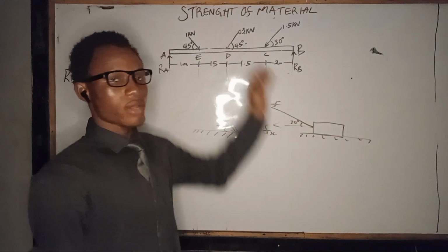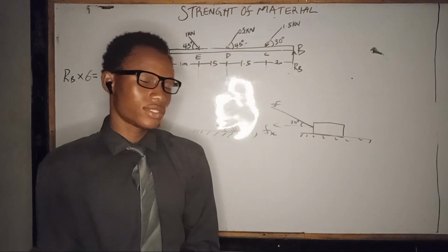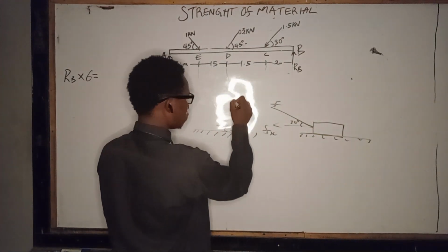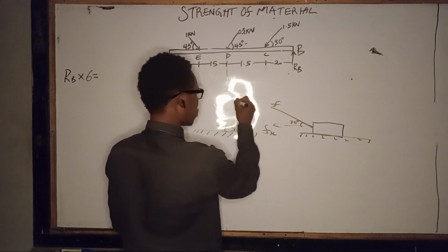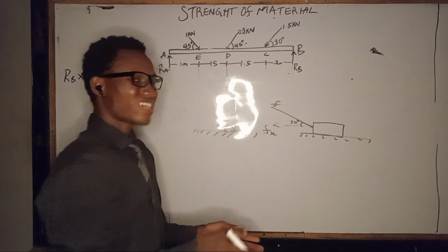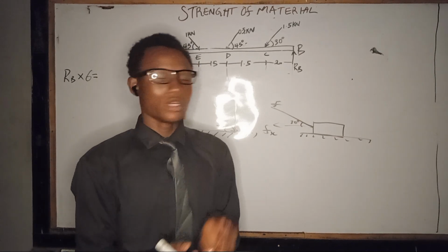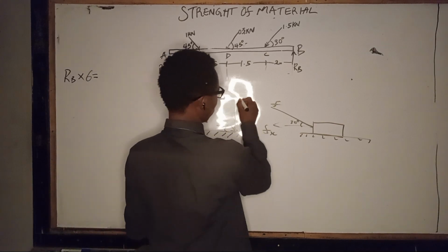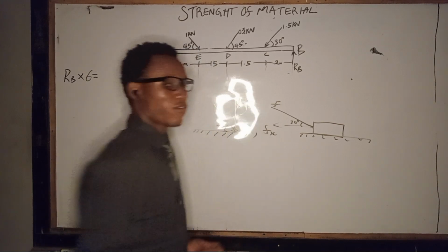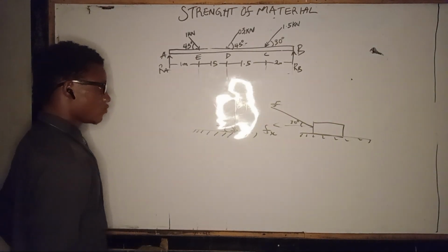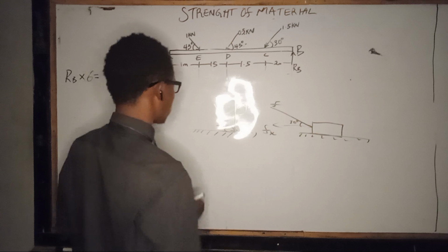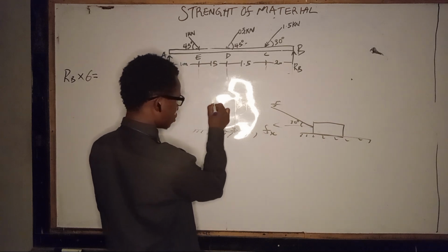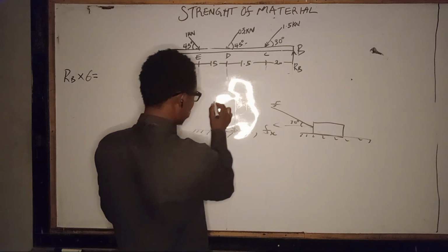But in this place, where we are doing shearing force and bending moment, what we need is the force that pushes from the top, and that force is going to determine how it will bend. So what we need to find is the vertical component, F of y. If you are to find the vertical component, let's imagine a triangle here, with the horizontal component as its base.